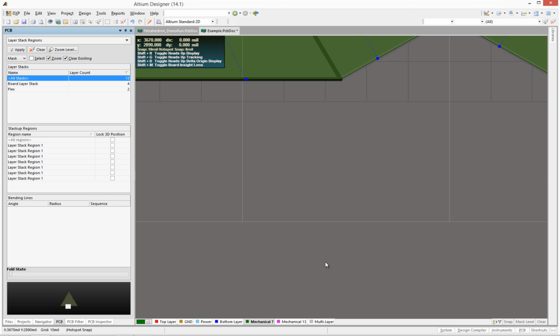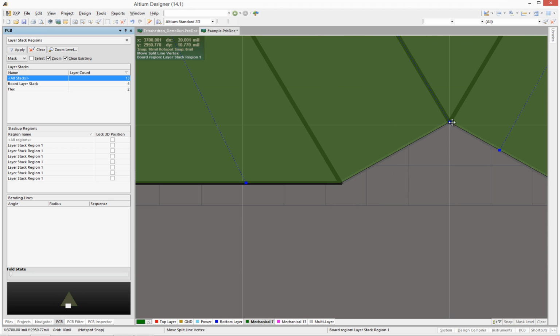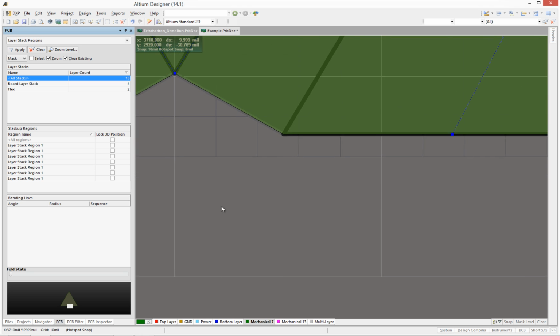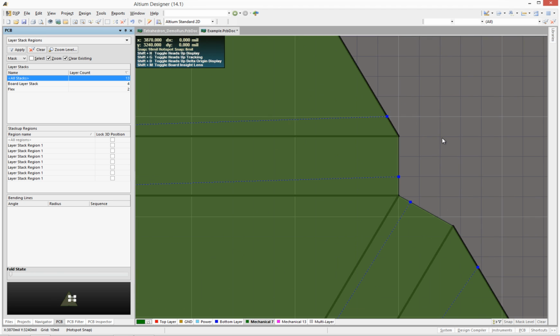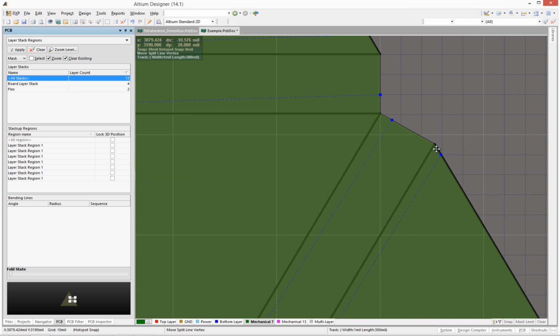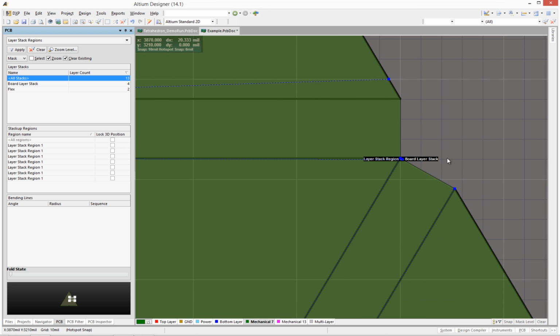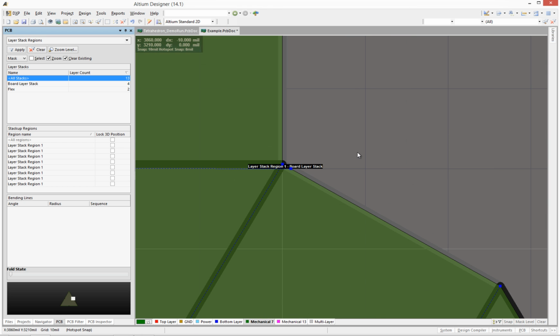All right, and let's page up here. And we'll push these up here. And we'll view fit. So when I do my view fit, I hit the letter V followed by the letter F. And I'm using my page up key here just to jump around, just to give you a quick reminder that when you're doing these panning and zooming, especially the panning, if you hit page up and page down on your computer, it's going to pan based on where your cursor is. Now you can see right there that I just crossed it, and if I don't fix that, that could be a problem. So let's make sure we get that right.